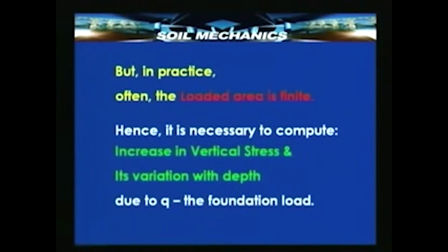Let us proceed further. As I mentioned, in practice very often this loaded area is finite, it is not very large, and therefore, we often need to compute the increase in the vertical stress and its variation with depth due to the surcharge Q, which is nothing but the load that the foundation is transmitting. So, this is merely emphasizing what I told, that it is the increase in the vertical stress that we are interested in.